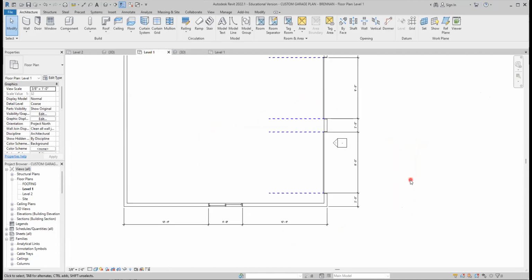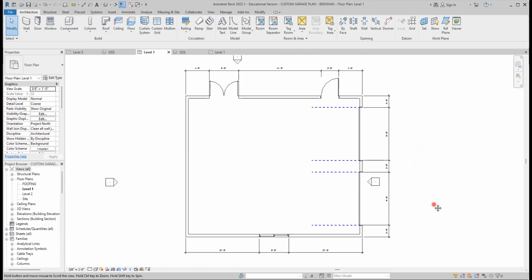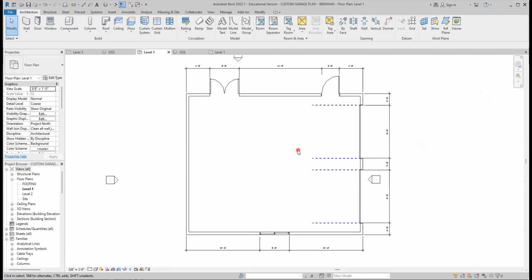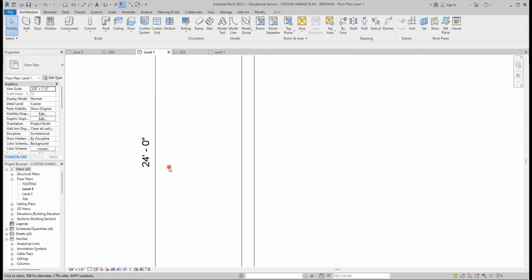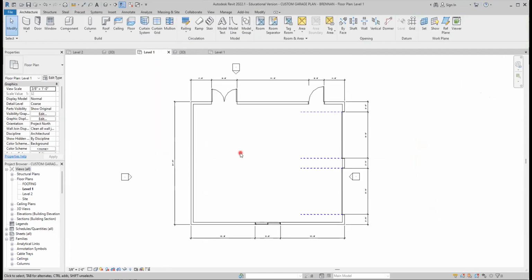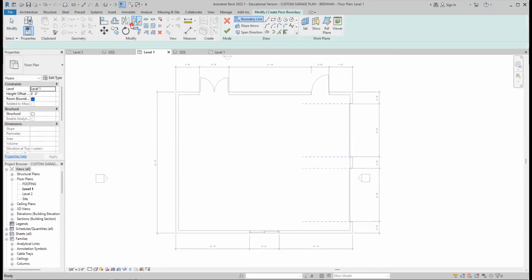We're going to put in the floor. So back to level 1, we're going to put in the floor. Now, before we do that, I'm going to put one dimension on this wall, make sure I've got this right. And I do, that's 24 feet, so we're good to go. Now to put in the floor, we've done this a few times. We're going to go over here to where it says floor, and we're going to use the floor generic 12 inches right here.